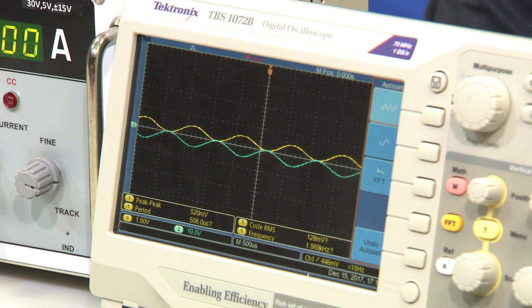So, applying 500 millivolts at the input, sorry, 500 millivolts at the input, what is the output, that we have to see, right. So, what we have seen until now is that when you change the input signal, based on that you can easily see the change in the output signal. One thing that remains constant is the phase shift, right. You see yellow and blue, these are out of phase.